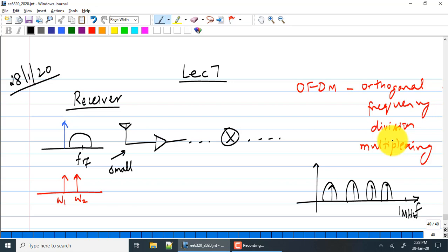Now, why do I bring this up? The reason is very simple. If you try to send such a composite signal into your receiver, you could in fact have interaction between the subcarriers, not just between interferers. Okay, that is all I mean. Here we have tones omega 1, omega 2 which are interferers, and we are going to find out how they interact with each other when they go through the system. But it is indeed possible that they are components of the signal themselves. I think that's a long-winded way of answering your question.